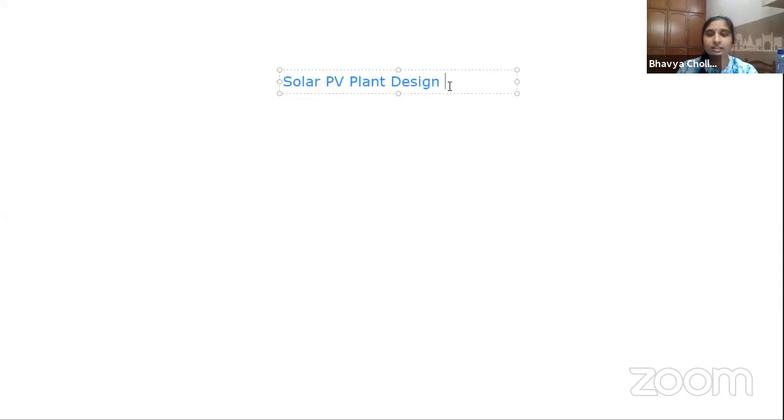Once you have done that, in most cases we check the shadow analysis. Then we also check the complete energy generation report and the irradiation level in various months along with the loss considerations. Let me put those in this Word document so that you will have an idea.